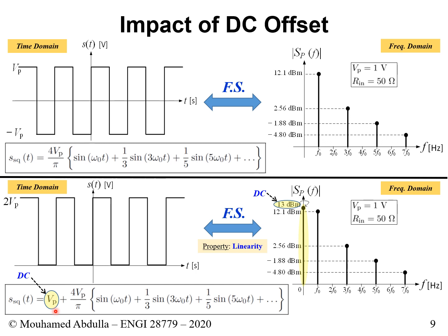Whatever the offset is, the voltage, you simply have to find its average power. And the way to find the average power is you simply use Watt's law. And we know Watt's law from electrical fundamentals. There's 3 ways to see Watt's law. V times I, I squared times R, or V squared divided by R. And the one that makes more sense for us is to use V squared divided by R because we have the internal resistance of the spectrum analyzer. So you find the average power. So essentially you take this voltage, you square it, you divide by the internal resistance of the spectrum analyzer. If it's not given to you, assume a 50 ohm.